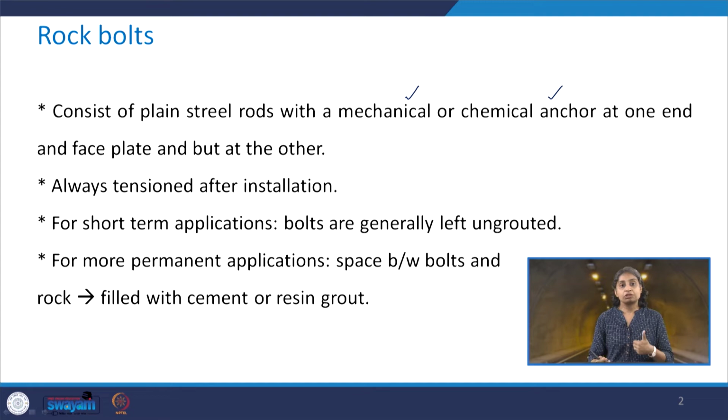For short term applications, these bolts are generally left ungrouted, but if the requirement is for a more permanent application, then the space between the bolts and the rock should be filled with cement or resin grout.